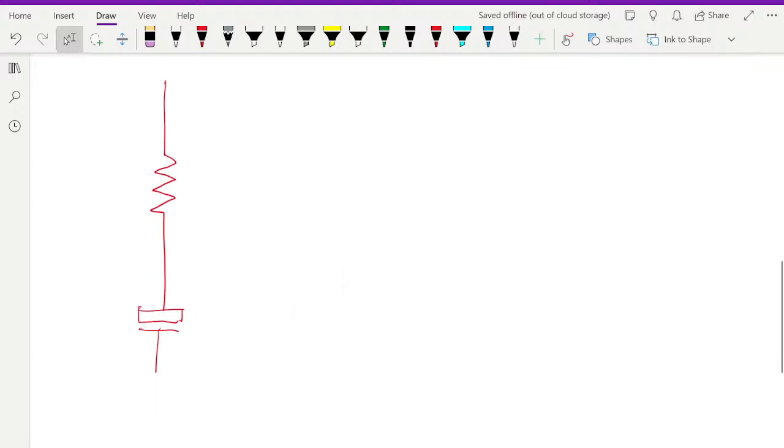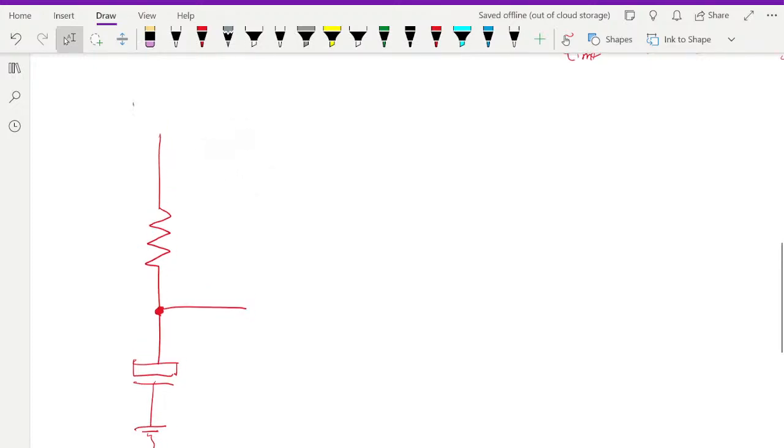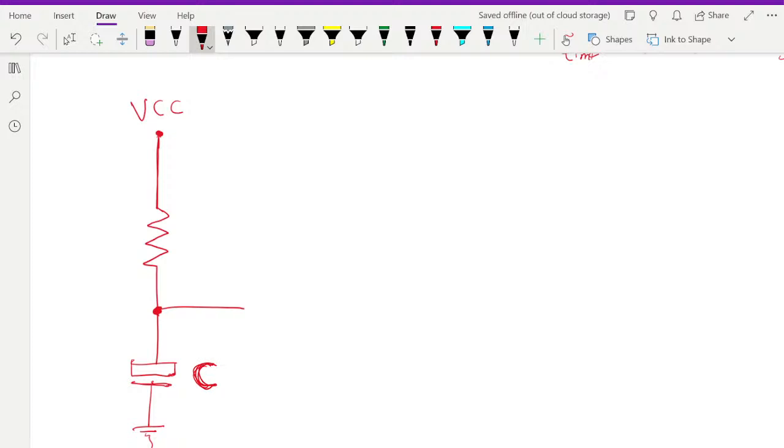I remember one time I worked in one company and they were having problems with SD card readers, and that was because of some issues with the timer in the system. It was supposed to reset, but it wasn't resetting, and they had used a very huge amount of capacitance on the actual circuit board, against the recommendation of the engineers who designed the system.